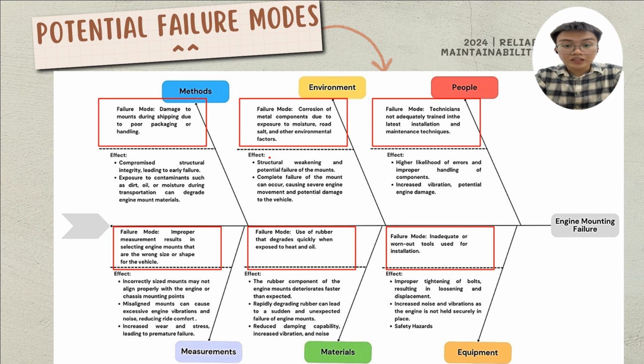Lastly, the equipment category points out that using inadequate or worn-out tools during installation can result in improper bolt tightening, loosening, increased noise vibrations, and safety hazards. This diagram illustrates how various factors contribute to engine mounting failures by affecting the mount's structural integrity, alignment, and durability.